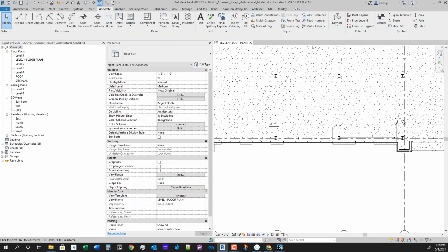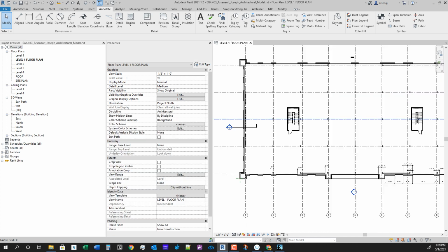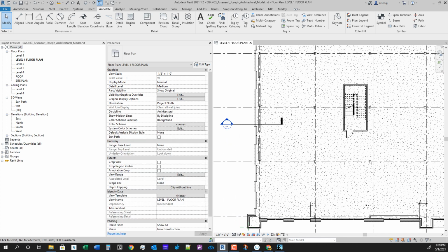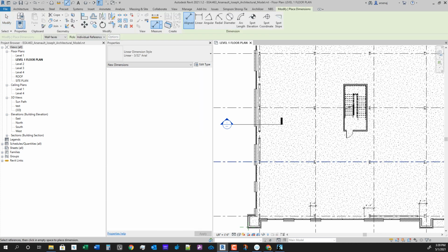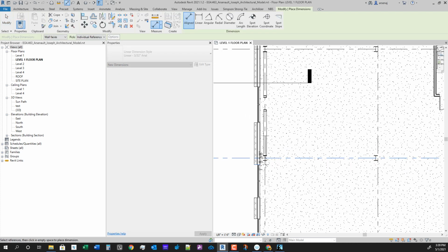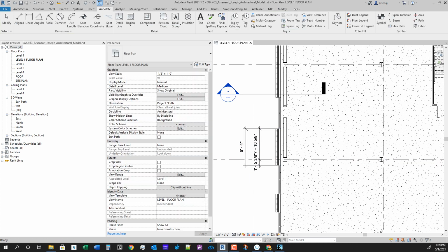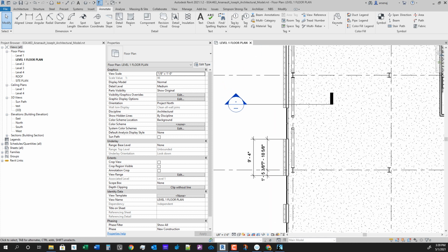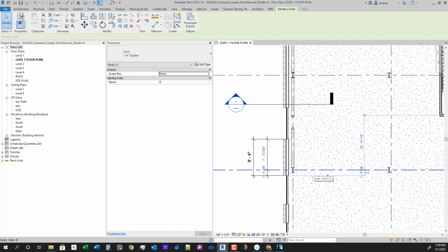Alrighty, so we did it there horizontally, which will affect both sides because we're just adjusting the grids. So let's do the sides now. I'm just throwing a dimension on both sides and then getting the overall, since we already know that throwing the equal on there isn't working because it's trying to constrain something else.